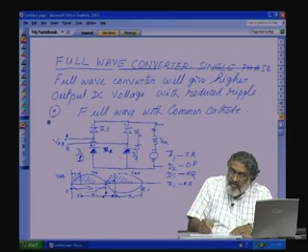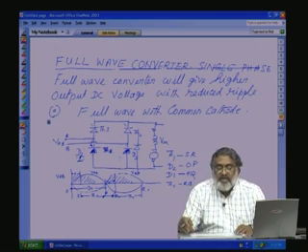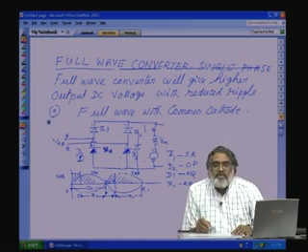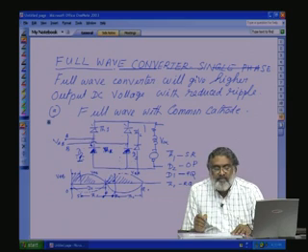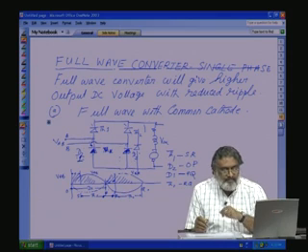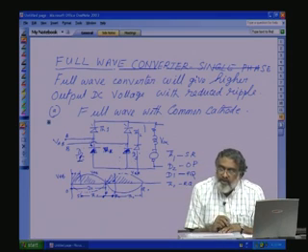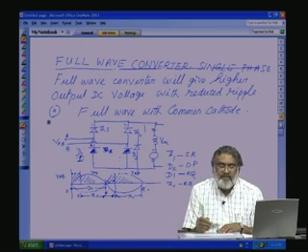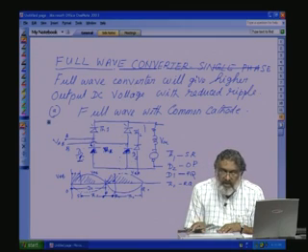But when we give suggestions for voltage control, we have to give a cost effective solution. The problem here is that because of the freewheeling diode, one more additional component has come. So this will freewheel through this one, but we can save on this diode by changing the configuration in some other way, another modification of this single phase full wave converter. We will talk about that now.